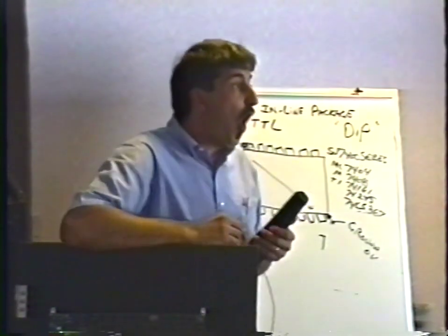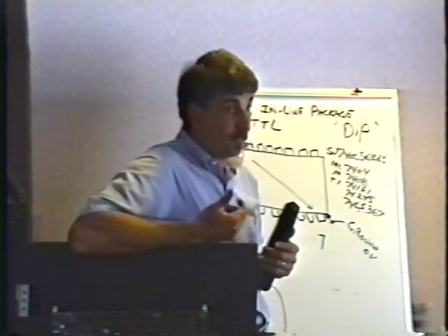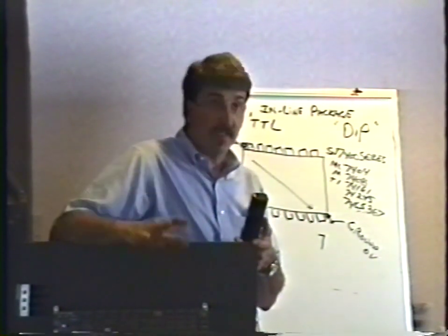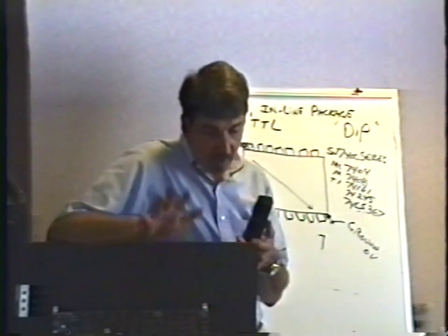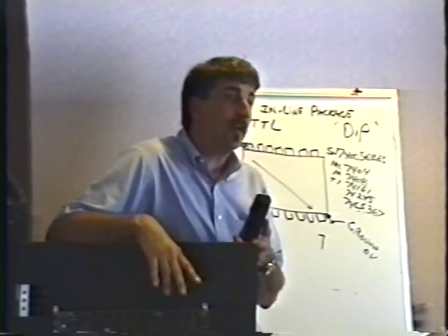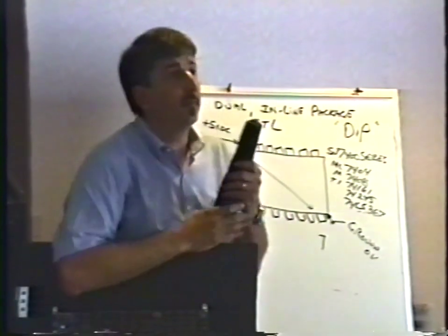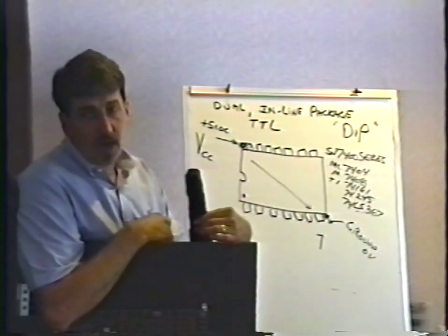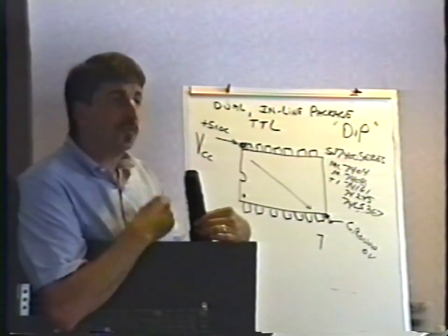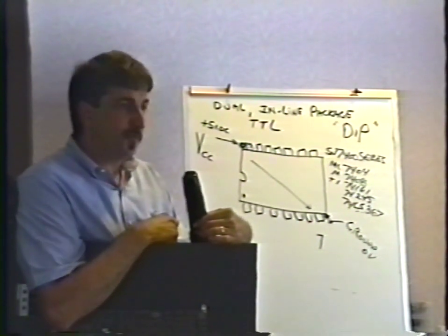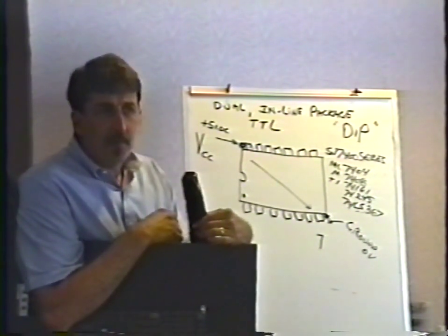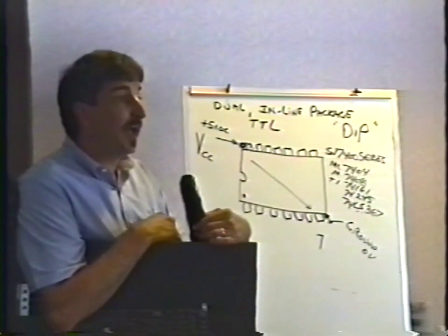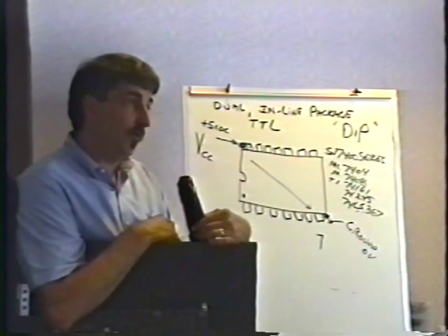Naturally, you always want to eliminate your power supply as a cause of this problem. You want to make sure that you adjust the 5 volts so that all that is perfect before you do anything to the board. And as a matter of fact, and this is pretty important, so try to remember this, sometimes you'll have a weird power supply problem where the 5 volts really does seem perfectly okay. When you measure it with your meter, it's 5.1 or whatever. But you have, I guess the best way to describe it is, a hidden power supply problem that your meter cannot locate for you.